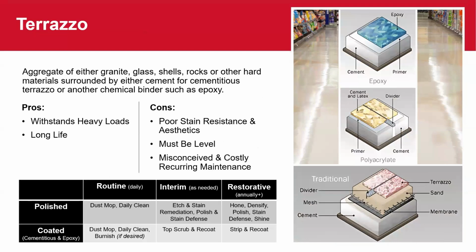Cementitious terrazzo withstands heavy loads. Actually, they all do, whether it's epoxy, polyacrylic, or traditional. Long life for that floor. One of the benefits of cementitious terrazzo is that it can be outside as well as inside, where the newer epoxies and polyacrylics cannot be outside, just inside. The downsides are poor stain resistance and aesthetics, mainly in the cementitious.